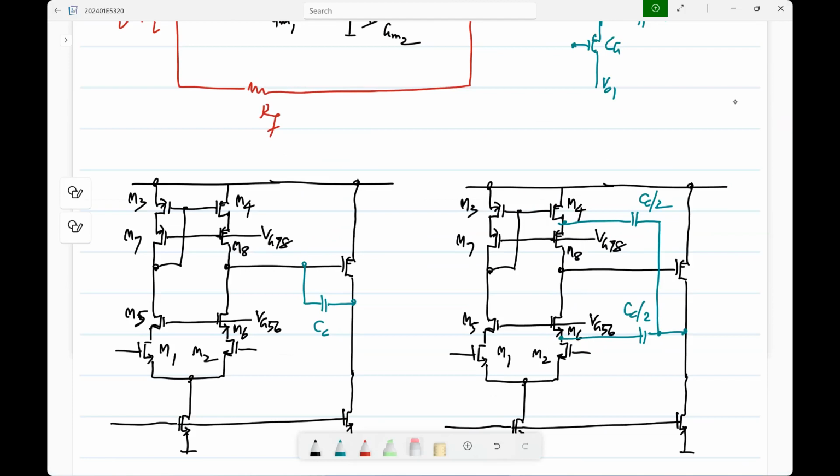Is it high or low? It should be 0 ideally. If the common gate amplifier was an ideal current controlled current source, it would be 0. But the swing is very small. So, basically, the swings here are very small, so this won't do anything to it. Right. Correct.